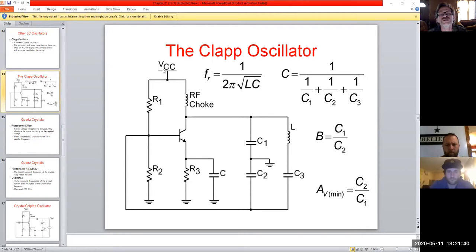Well, we just basically apply a DC input to this thing, use the amplifier as it is here, setting up our time constant, if you will. Okay, so we have this tank circuit, L and C, right? And remember how inductors and capacitors are as far as phase opposition goes. So the inductor wants to swing this way with phase, right? Remember ELI the ICE man? Well, that's a real thing. So we set them into opposition of each other to try to swing it more where we want it, right?